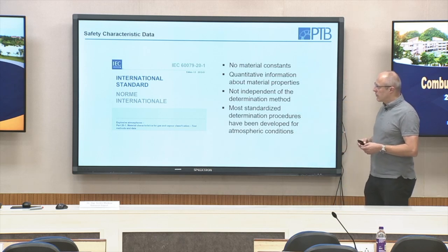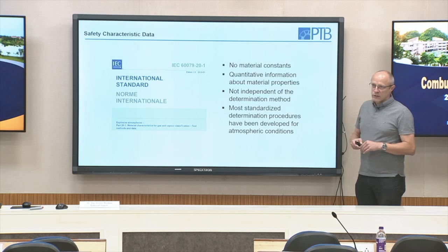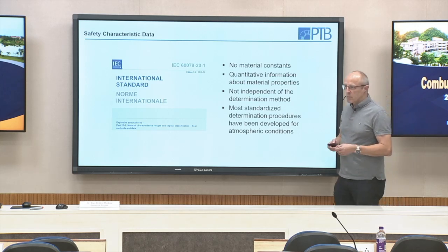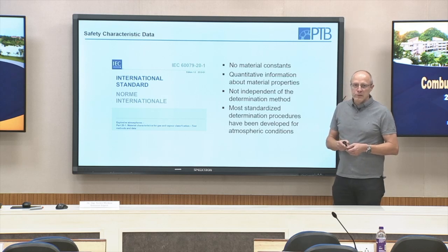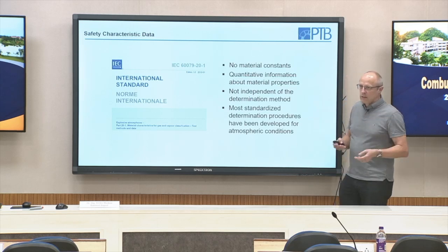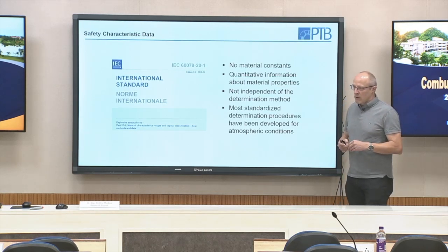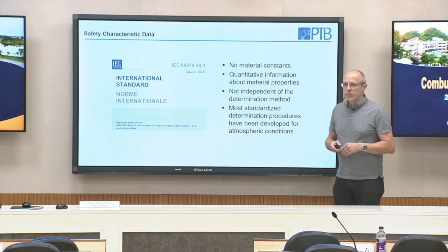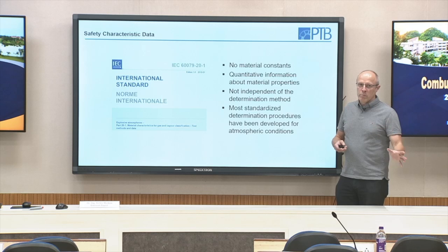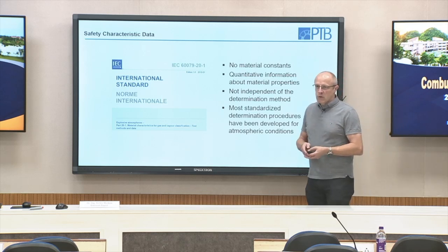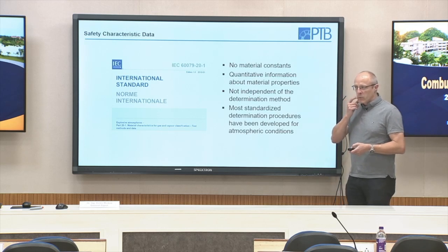We can use this concept also for the so-called gas groups. So for the chemical and petrochemical industry, we separate all the combustibles we have, and we have thousands of them, into 3 groups: 2A, 2B, 2C. And the proper equipment we want to buy to consider safety is focused on the group we need.